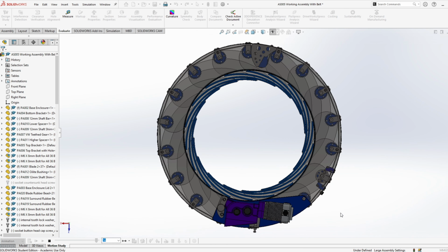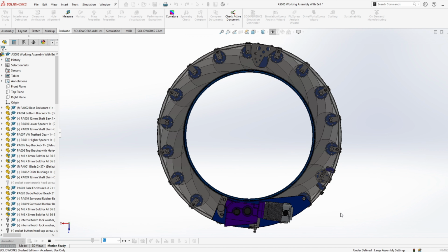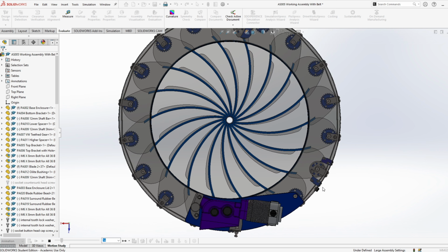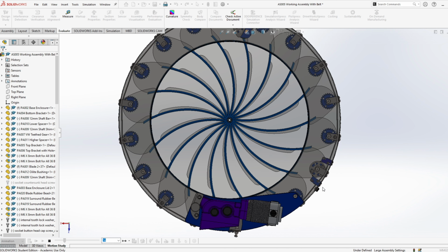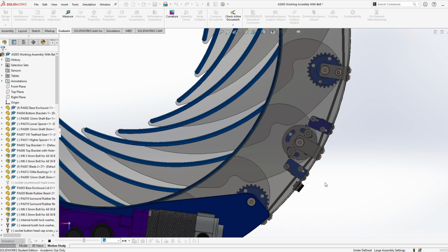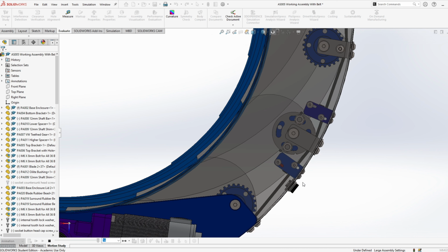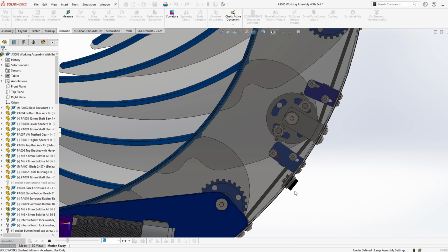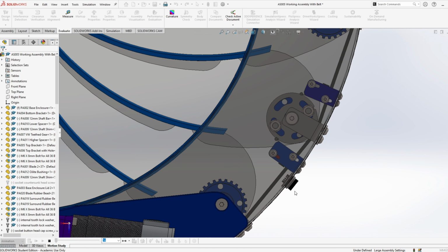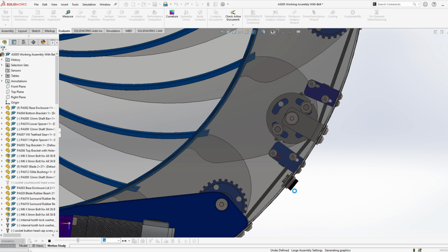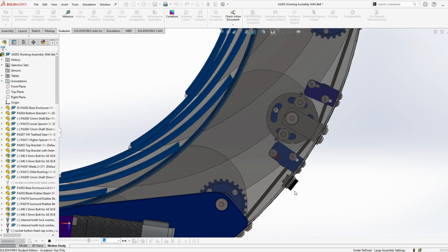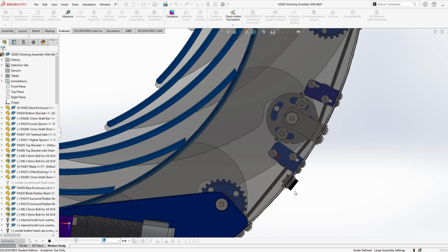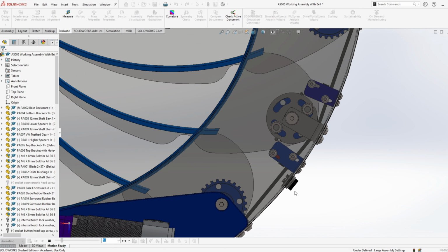Also seen in this area of the aperture is a miniature 8-pole connector, mainly for the attachment of these very important limit switches. So I have specifically placed this connector here to keep the wire lengths minimal leading to these switches, where this directly connects using a cable to a control module I created for the system, which I will demonstrate in part 3 of the project coming soon.